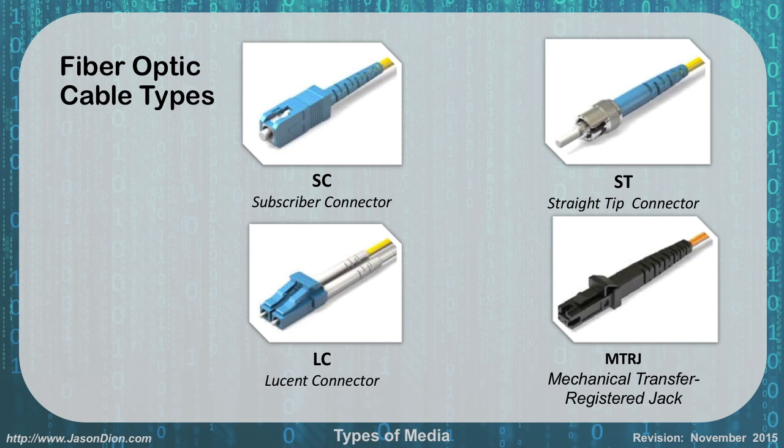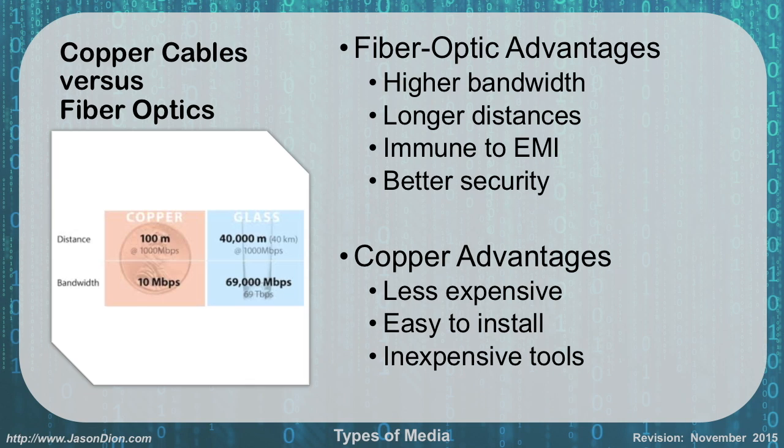And it's 2 fibers in one single cable, and they are very, very tiny, usually used from routers and switches to each other. So you can get more fibers in a smaller space. So oftentimes you'll see the MTRJ on one side and the SC or the ST on the other side. So going from the switch to a PC.